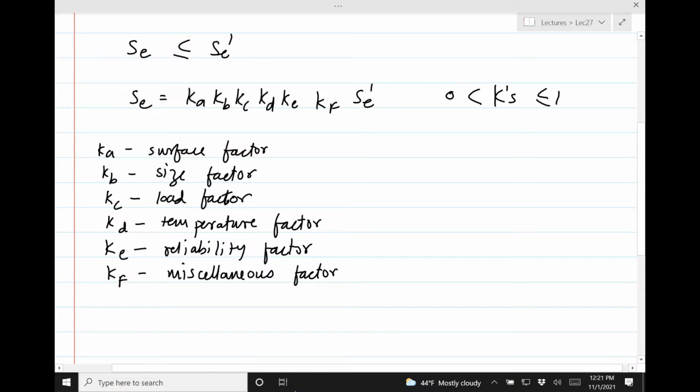Okay, so one way of figuring out what SE is, essentially it boils down to a bit of physics and making up theories why each of these factors would affect the stress and the endurance, and then having a model based just on the material properties, right? But the other way to do it, and which is the practice followed in machine elements, is we don't really do too much to build a theory behind why the endurance is low based on the microstructure. We just do tests, and once the test results come out, we make up a factor by sort of fitting data. And that's the approach which is taken here.